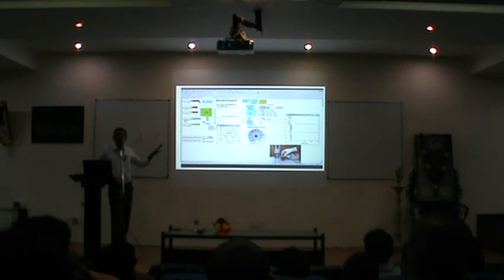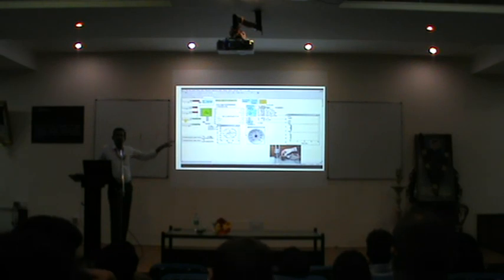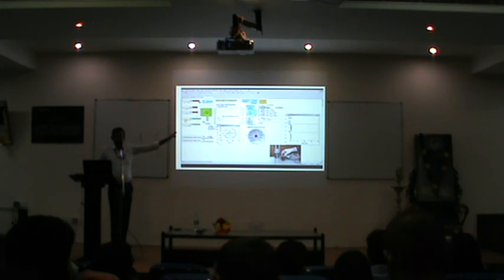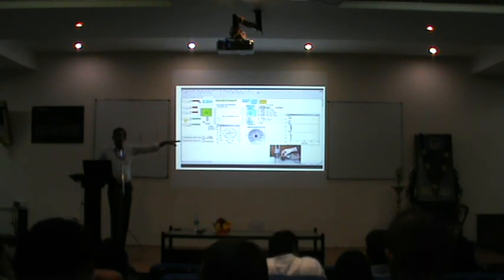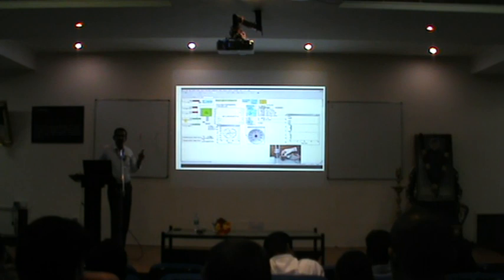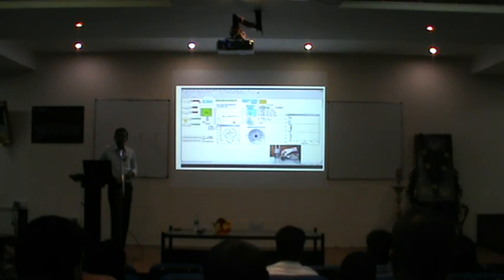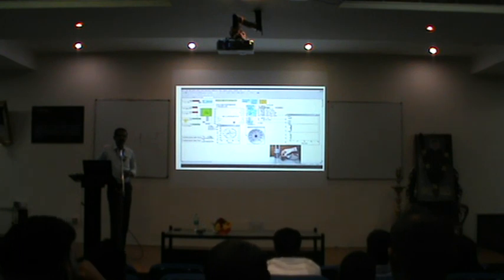So you just monitor, and this is the final phase of development. You had model-in-loop simulation, then software-in-loop simulation, processor-in-loop simulation, and hardware-in-loop simulation. HIL comes at the last stage of development. That HIL implementation is what you see here. Once again, these kinds of provisions we don't see in non-model-based design tools.